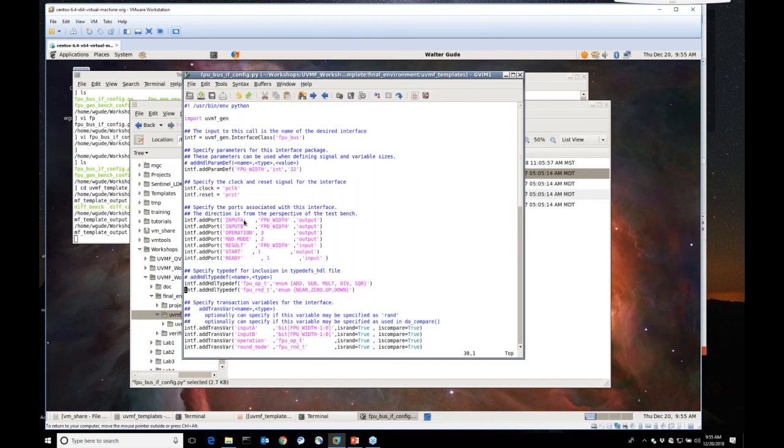For every operation I'm going to do, I'm going to load up input A and input B, I'm going to load up what operation I want to do and what type of rounding I am looking for. I load up those things. I send the start signal, and then I wait for the ready signal to come back, and I read the result register. So that's all the ports of my FPU.